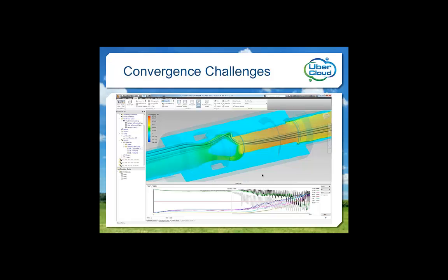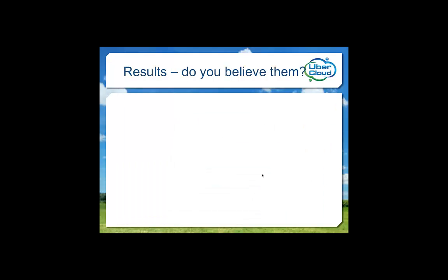Somewhere in the enormous matrix Simulation CFD was trying to solve, there were static pressure values that were dipping below the vapor pressure of water, less than 1 psi-A. Thus, for an instant, the incompressible fluid was now a gas. Looking closely at the dithering, I could just imagine that instantaneous change of fluid velocity, fluid density, caused an overshoot that led to another change in density.